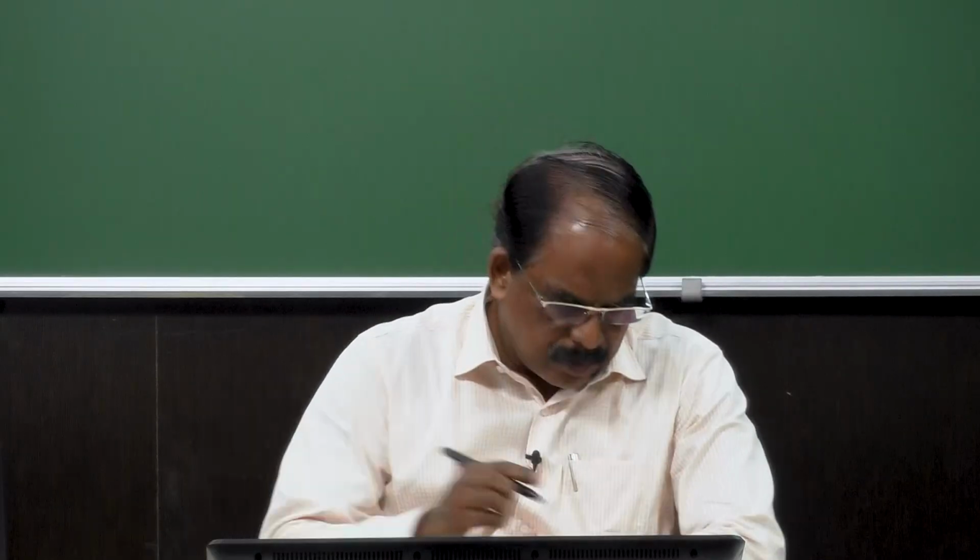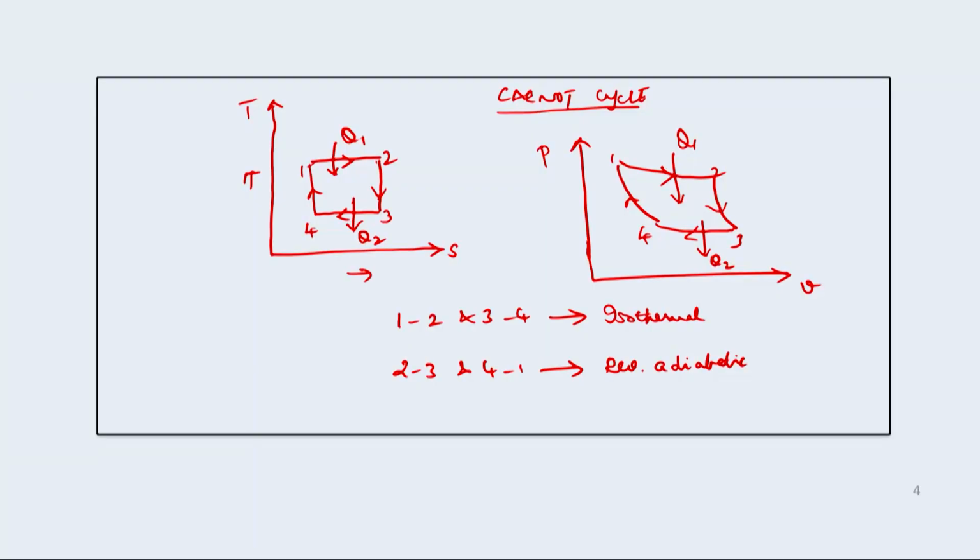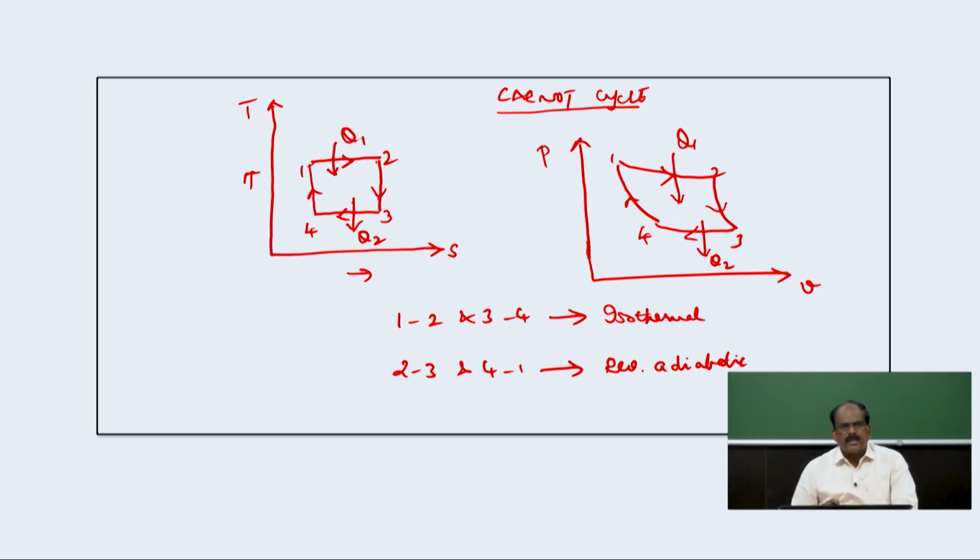When we come to the refrigeration cycle, the reversed Carnot cycle is the basis for comparison of the performance of a refrigerator or a heat pump. Let me again repeat, the Carnot cycle is the reference cycle or the base cycle for comparing the performance of an engine operating between a source and a sink, and the reversed Carnot cycle forms the basis for the principles of refrigeration, where we can compare the performance of a refrigerator or heat pump with that of a reversed Carnot cycle.